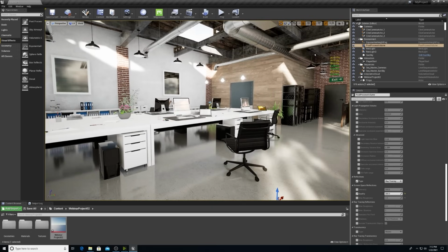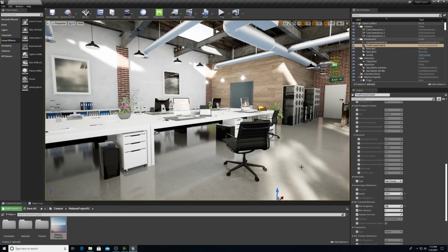So one thing that can help you control the performance there is going to be the max roughness, the max bounces, and the samples per pixel. So you'll see that this top number is set to 0.6. So this is the maximum roughness value that ray traced reflections will be visible before falling back to raster methods. So this means that when I put this to 0.3, the materials with a roughness greater than 0.3 will use raster rendering, which is a little less expensive.